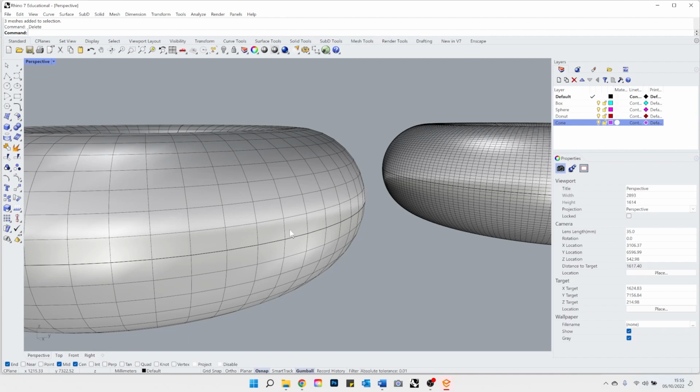So you can straight away see how dense the mesh is, that you cannot see the color of the object straight away. One or two objects like that in your model will be fine. If you start having plants on every single floor of your skyscraper, your file is going to get too heavy because every single plant is too dense. So what you need to do is use a command called Reduce Mesh. You can reduce the amount of polygons that your mesh consists of.